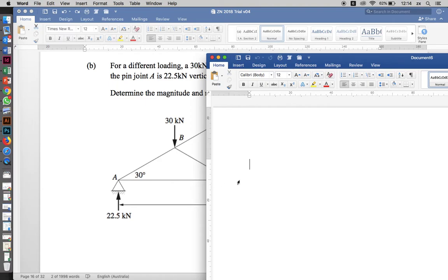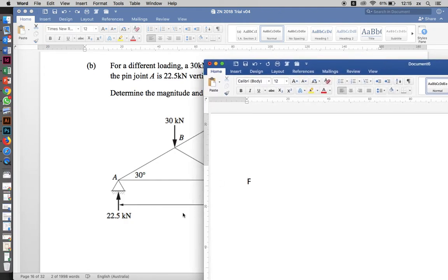So we're going from point F, which happens to be there. If we go with point F, we can ignore that one and that one. So now we have to measure our distances. Measuring from point F, we're going to have 3 forces: BC, this 30, and this 25.5. We ignore these ones because they're both 0. They're 0 because the perpendicular distance to F is 0. Anything multiplied by 0 is 0, so we can ignore them.